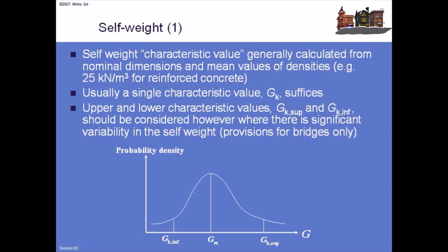So essentially on this bell curve again, we're designing in the middle here, we're not actually looking at variations in the thickness of the slab or in variations in the density. That will be taken into account in the gamma factors, generally. However, there are some exceptions.